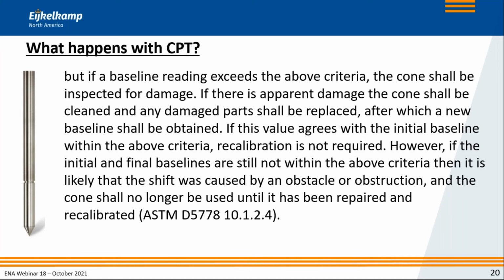And then when you replace those parts, you can do another baseline reading. If you find that at that time the baseline readings meet the requirements again, fine, no problems. But if not, then you can no longer use the cone, and again, shall no longer be used, a mandatory requirement, until it has been repaired and then completely recalibrated.